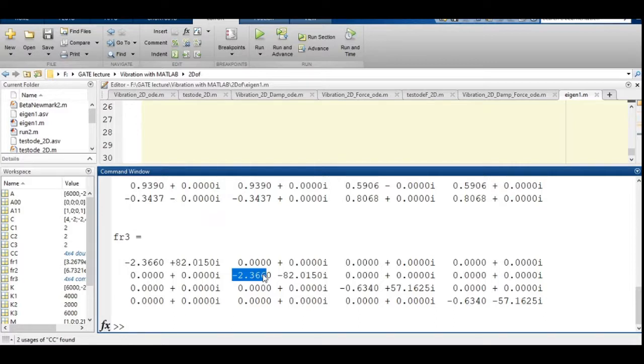If it were positive, that means because of the damping, the amplitude of the system will grow, and it is a problem where we are talking about flutter kind of phenomena or negative damping or self-sustained vibration. So this is a different topic. There, what we do is the eigenvalue analysis, and when the system becomes unstable, our eigenvalue solution gives the limit.